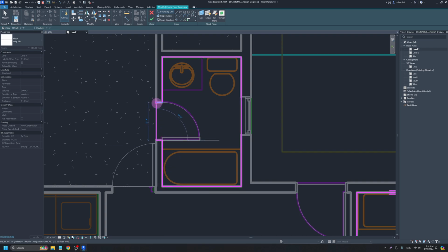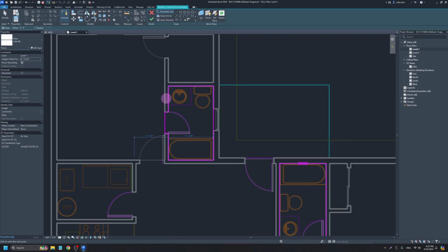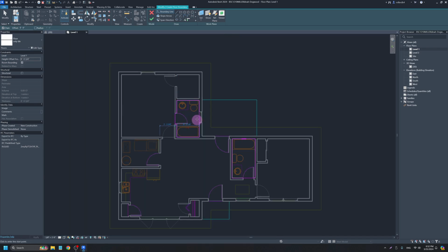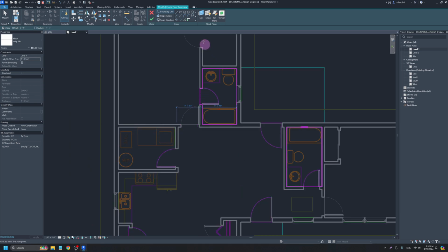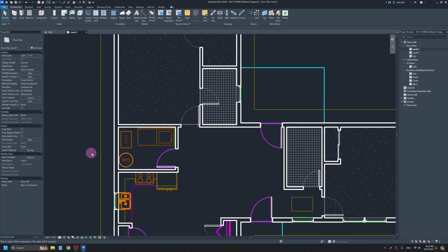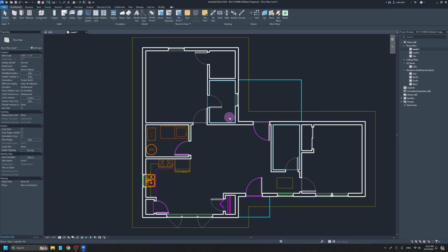And you always want to make sure you're making a closed loop. It has to be closed, fitting together spaces. Maybe you want to put tile in here as well. I'm just going to leave that for wood. So I'll click OK. And now I've got my tile finish in the bathroom.